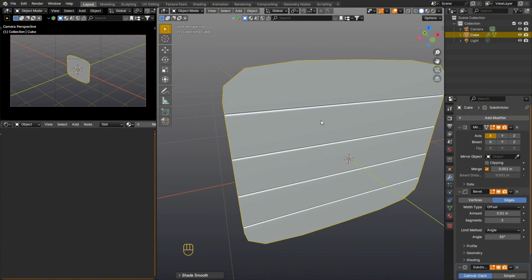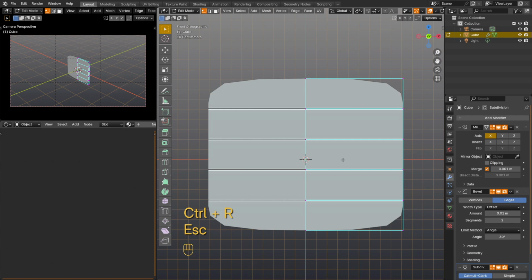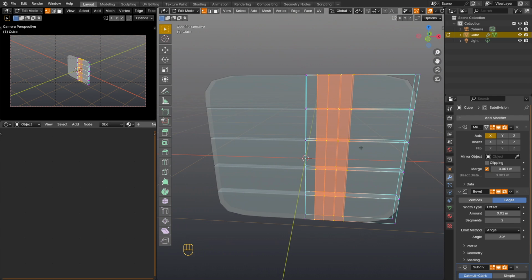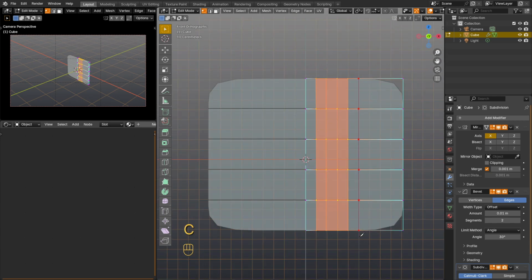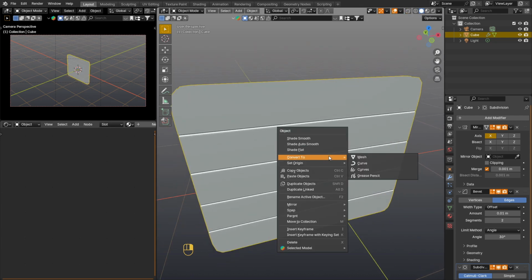Now, since in the future we will give all the parts of the build the shape of a lens, bend them. For this, all the elements must have a sufficient number of edges, that is, we need to add vertical edges. We will do this with the knife tool, but when we use it, we press the C button to cut through. When we are done with this, then we press the right mouse button and convert to mesh.